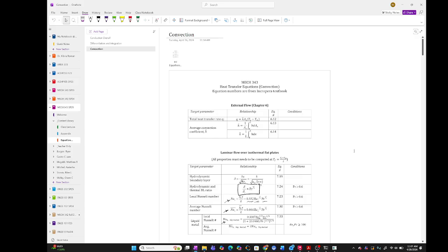Everybody understand? The importance here, in terms of heat transfer, is that the Nusselt number and everything changes, meaning the equation changes. Just like in external flow, you have seen the equation changes when you are laminar, mixed, or turbulent; all have different equations, right? The same thing is here as well. Also, just like in external flow, constant heat flux and constant surface temperature have different equations. Everyone remember that? The same thing is here too.